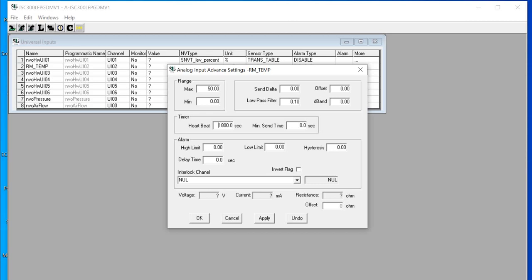The thermal count is fluctuating like 1, 2, 3. If that happens, you break the wire and measure directly at the sensor side. You see whether the voltage is stable or not. You disconnect, don't connect to the DDC. Your sensor is here, right? The DDC is here, far away, right?